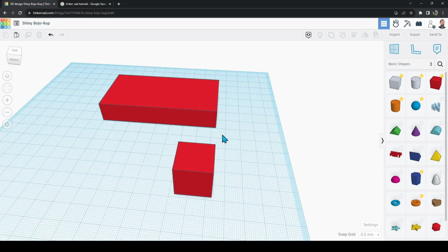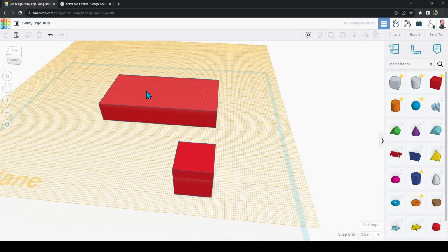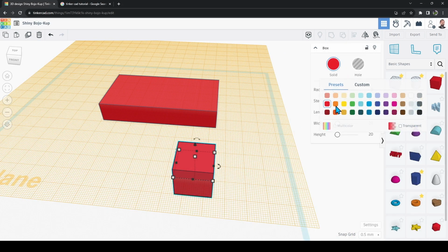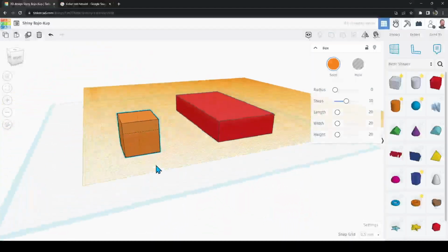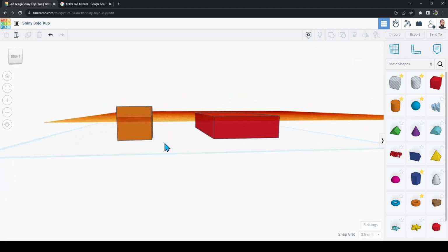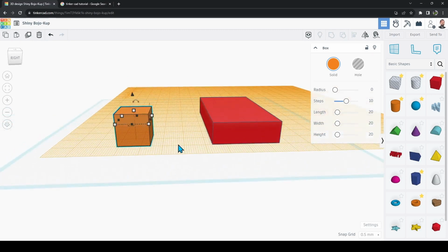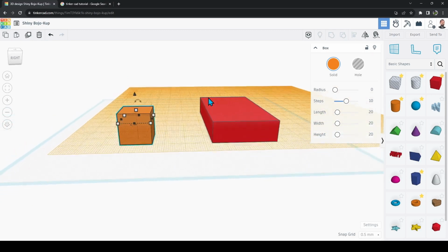Okay, let me show you something else. Right here up top, we have the work plane tool. What that allows you to do is work off of the plane that you're able to see on an object. As you see here, I click the work plane and I'm clicking on top of this face of this object. I'm going to change the color of this first. When I press the key letter D, it is going to place the bottom of this cube with respect to the plane that's above.